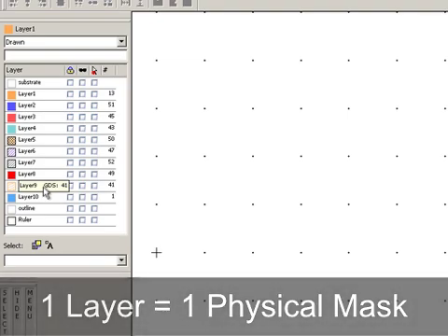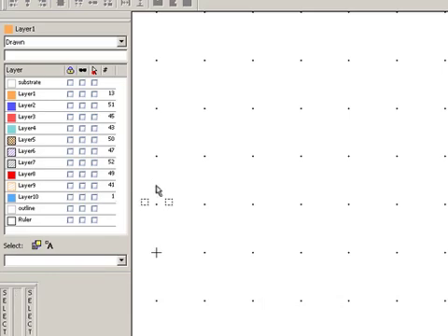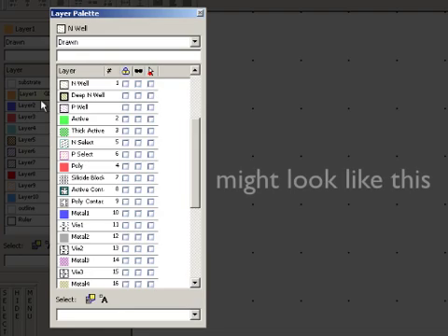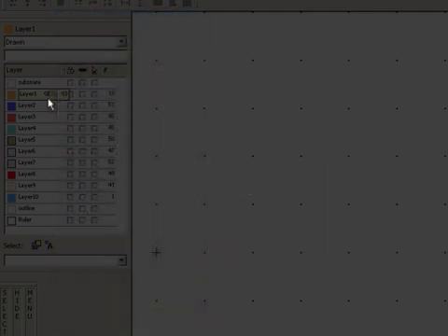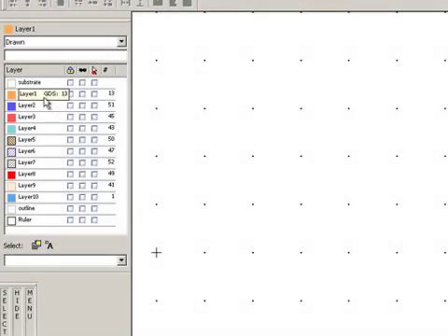If you're not working in NanoFab or you're using the default design environment supplied with LEdit, it's going to look quite a bit different. You may have quite a few layers, and they will typically have names like Metal 1, Metal 2, Vias, Polys, all these different names that are associated with actual materials. In our case, since we're doing our own fabrication, our own processing, we don't have any association with any distinct materials for each layer, so you're free to draw whatever you like on whatever layer you like, because you'll be doing your own processing later on.